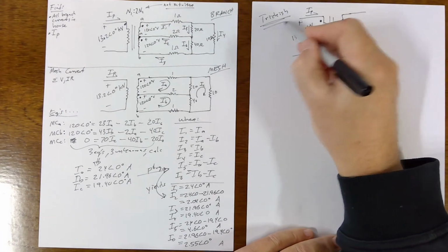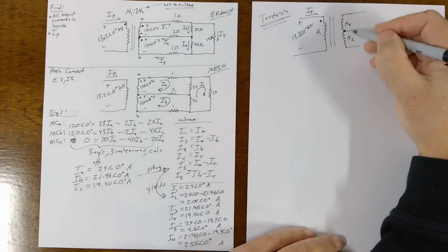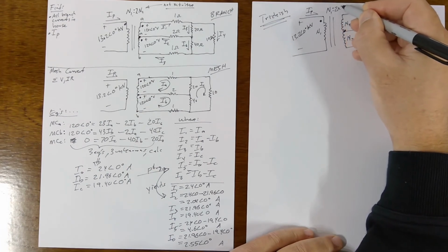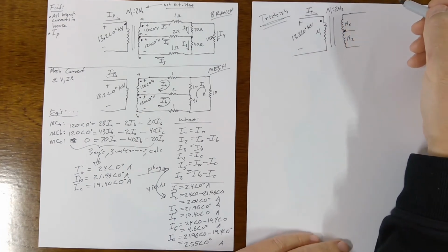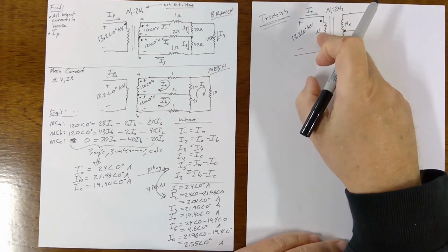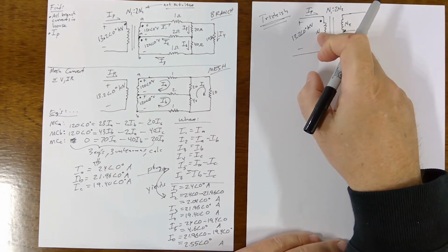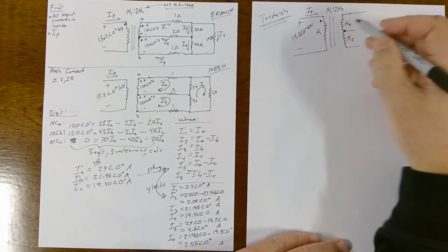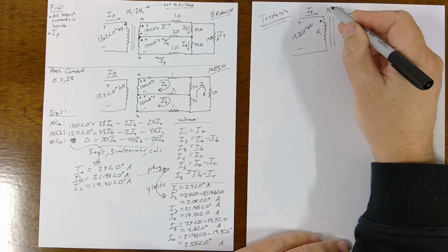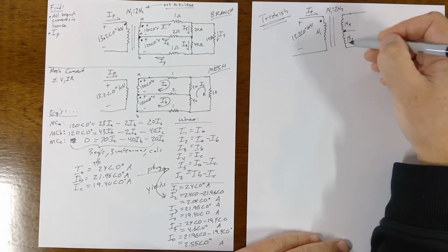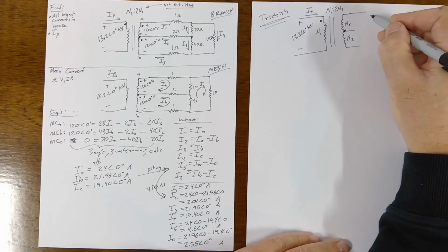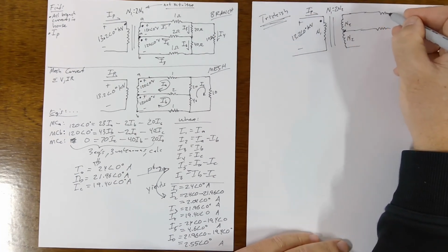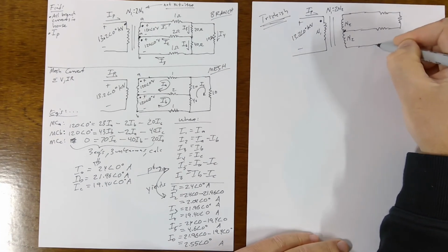It's kind of a trick, splitting this up into two pieces. And then we could say that the winding ratio is N1 to 2 N2, because it's the number of windings on this side, colon, the number of windings on this side, and there's 2 N2 windings on this side. This is just a way of writing it that matches this diagram that makes the math a little bit easier. So, trick. So, drawing this.